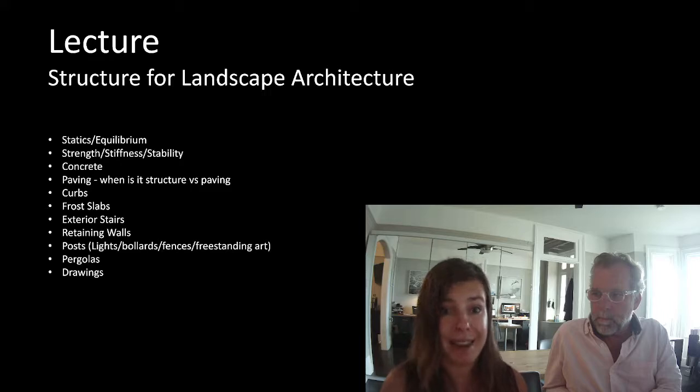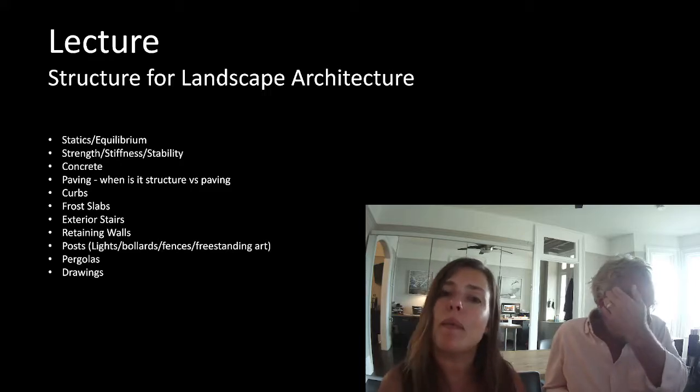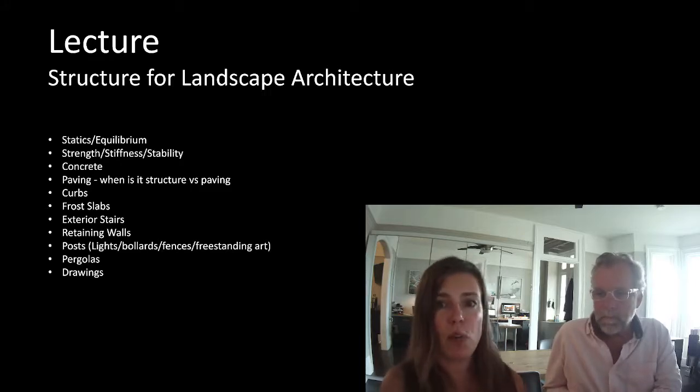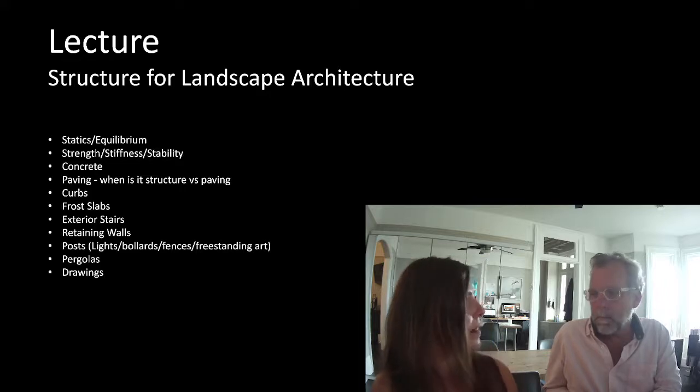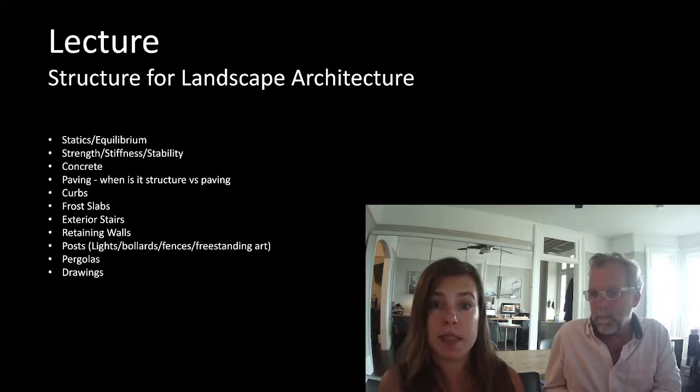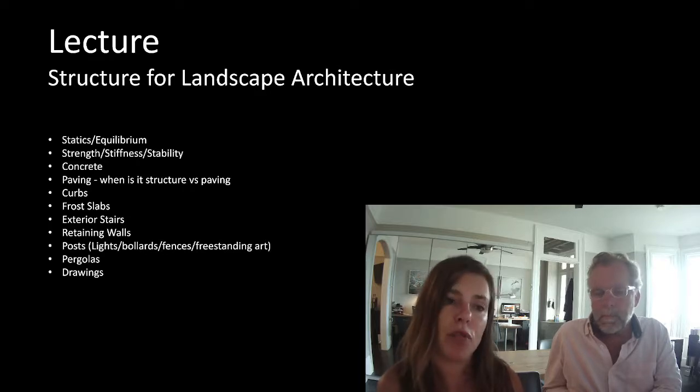It's buried, it's hidden. So we're going to show you a few images so that you have a sense of what it looks like. Because that's probably one of the number one issues that we see come up: in the tender process, retaining walls, for example, aren't drawn big enough and they end up being underestimated, and then an extra is needed during the construction phase.